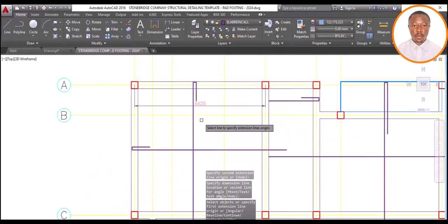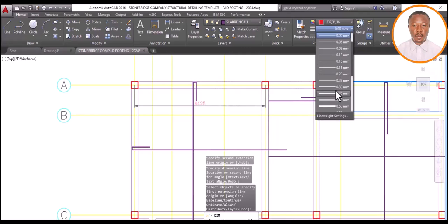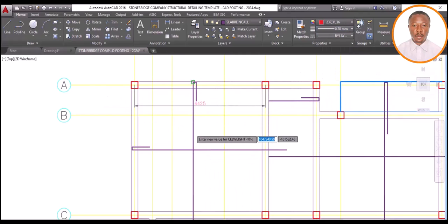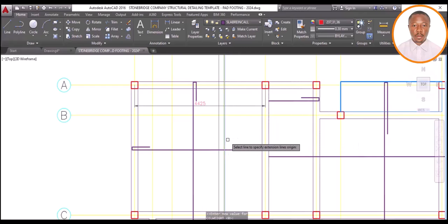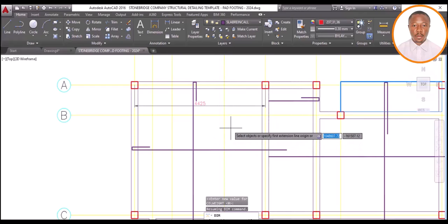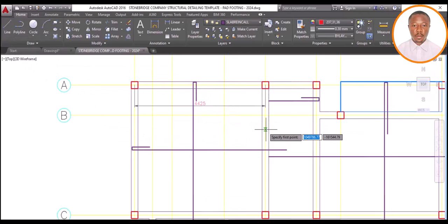So how do I go about it? Let me change my color and take my reinforcement. I want this, then my thickness, I pick this. To differentiate between the top reinforcement and bottom reinforcement, it has a principle, and the principle is 25% of our slab length. So I pick my reinforcement. I see it as my reinforcement because I'm acting as if I'm at the site. So I will say it's 1,200 into this slab.